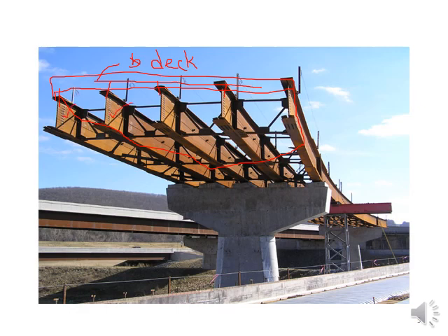You can see in this figure for this particular bridge, 1, 2, 3, 4 and 5 girders are placed to carry the load coming from the bridge deck, and you cannot see the floor beams here. Only the diaphragm has been placed for stability purposes. Here you can see in between, this is the diaphragm. The diaphragm has been placed at a constant spacing along the length of the girders, and you can see the transom, as I have told you. This transom is a laterally placed member, so this whole structural element is the transom.